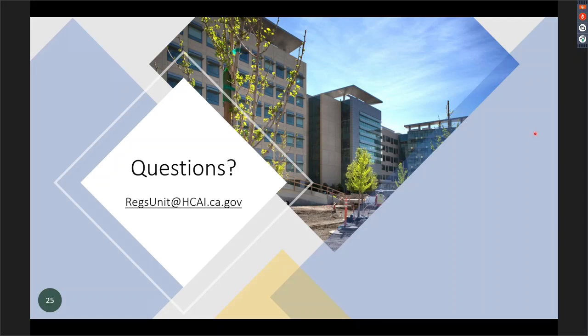Now you're adding something that's typically non-material, but you're changing what's on the drawings. Say you're missing an exhaust duct in a room, and there's nothing showing where it's connecting to. You're now adding that duct run to answer that RFI. That can be considered non-material. It's not material, but it wasn't there. You're adding something to the drawings.